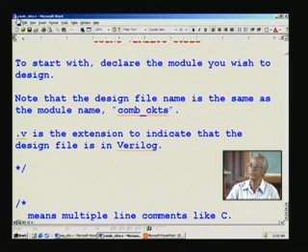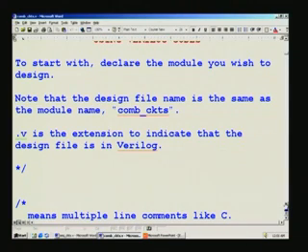And once again I repeat that com circuits is nothing other than your module name, and the file name should match with that. You cannot nest multiple modules. In fact, I mentioned this in an earlier lecture also. If you have different modules, you have to put them in different files and call those modules here, and what we refer to as an instantiation. We will go into depths of those later on. When the design gets more and more complicated, you have to resort to such methods.